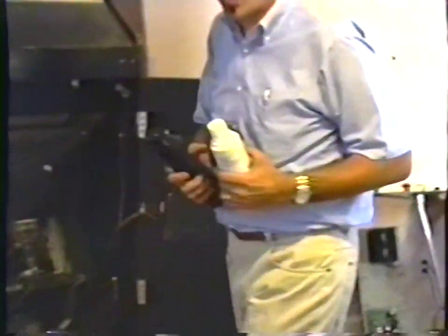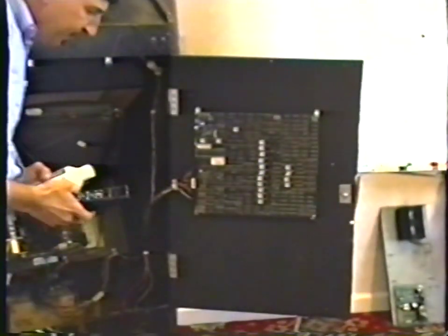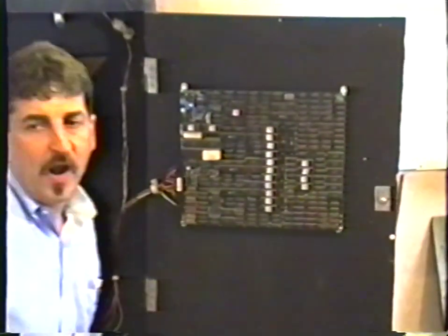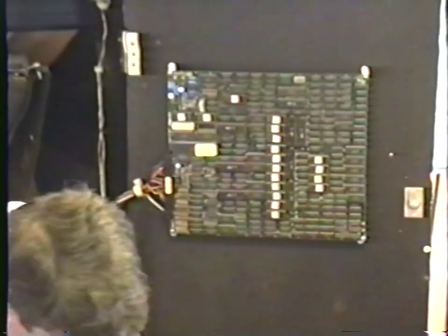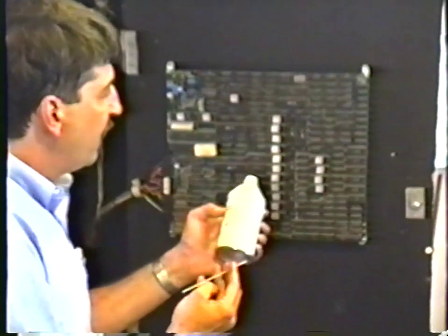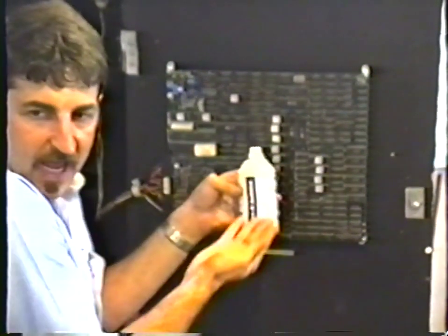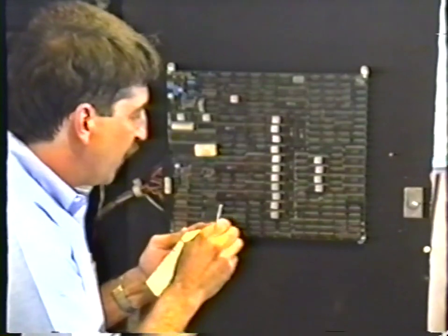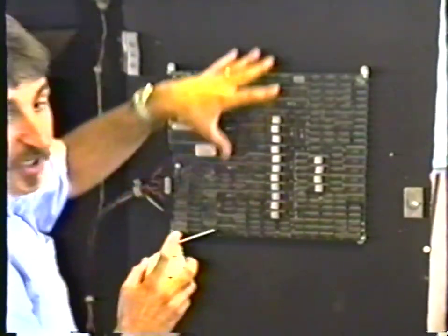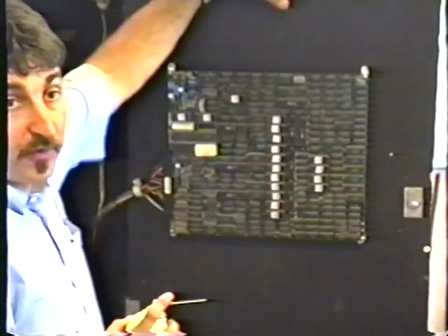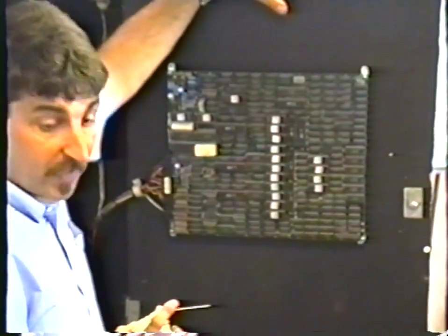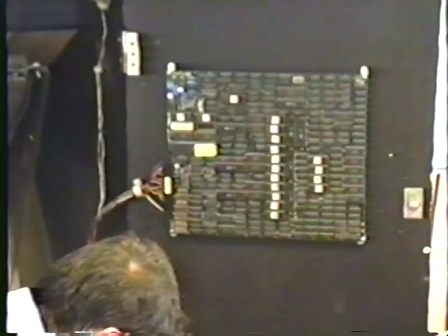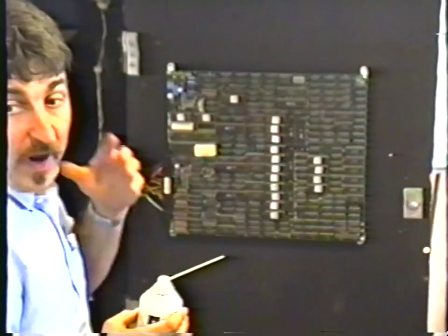When you have a problem with a board where it is thermally intermittent, that is, when it's cold it works okay, but when it's hot it doesn't, you use this can of freeze spray. And what you do is this. First thing you do is you have to heat the board up so that you actually have the failure. You have to actually have the failure, obviously, first before you do this. There's several ways to do that.